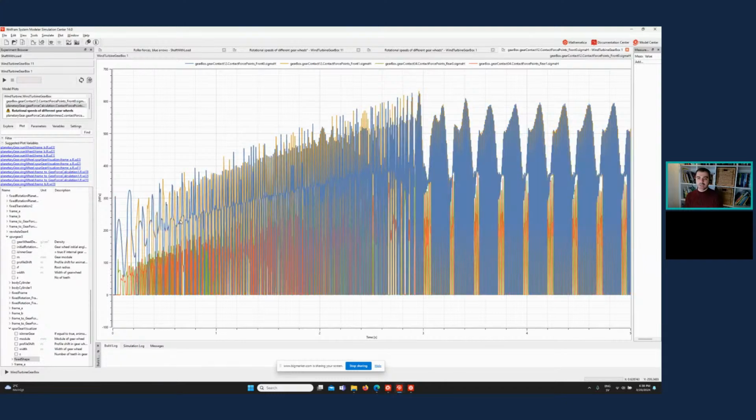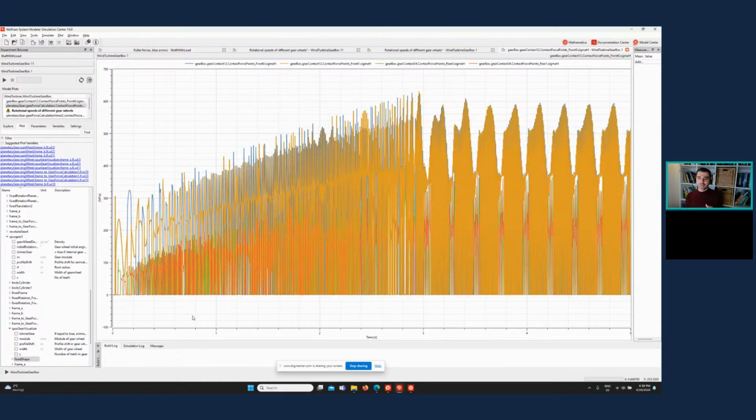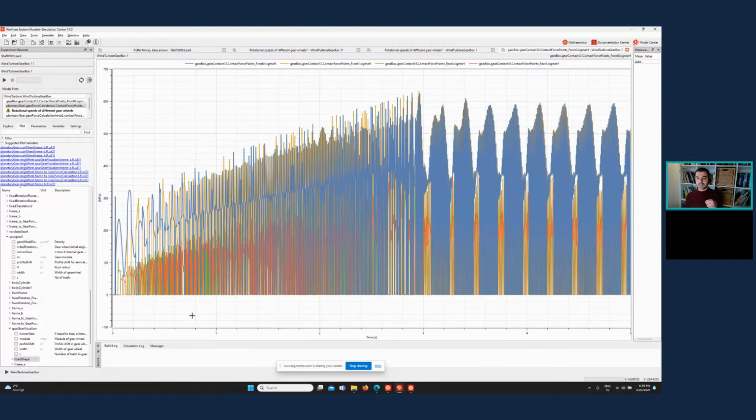All the forces are created because of the propeller speed, and the computation of these forces takes into account the Hertz contact theory and responds to the frequency characteristic of the load as well. Depending on that, we see what type of stresses we develop. Also, we can check the indentations, how much deflection we have in the teeth.